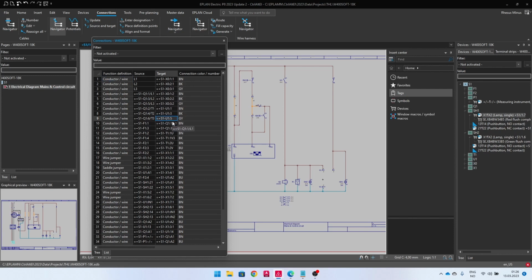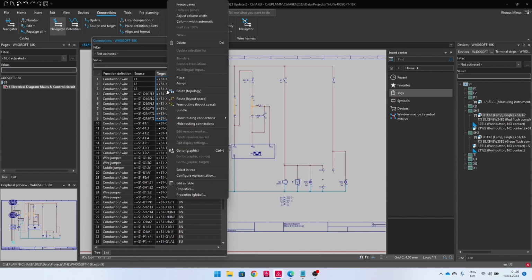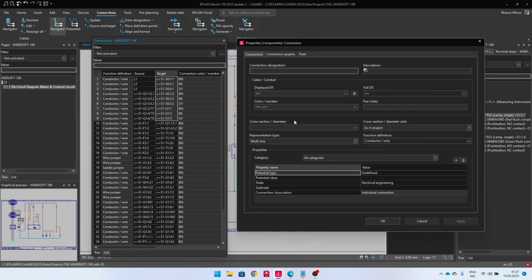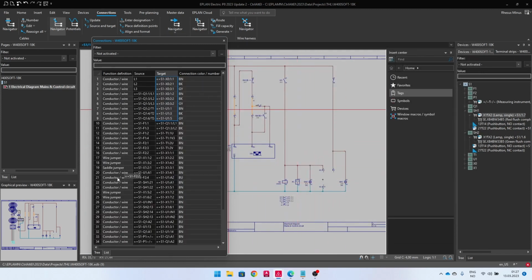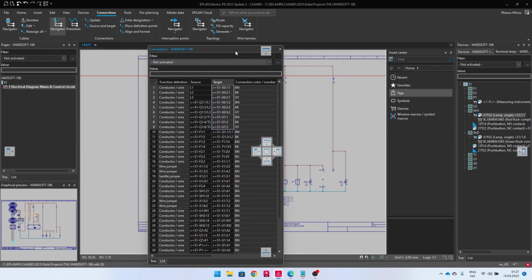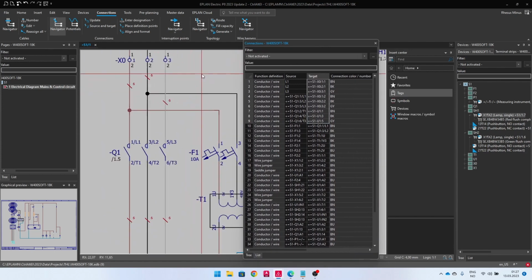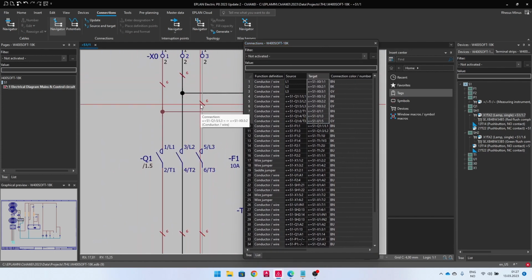And down to the soft starter. So I will just select all of these. I will go for properties and I say, well, these are 6 square millimeters, like this. And you can also see when I select something here, I can see here also what connections I am working with. And if I look into my schematics, I have some objects placed here as well.